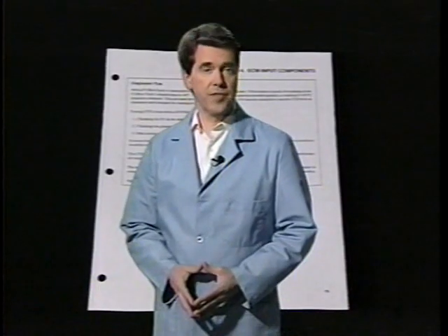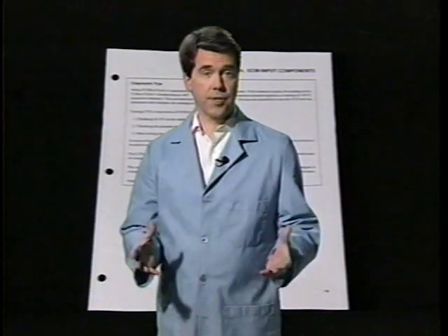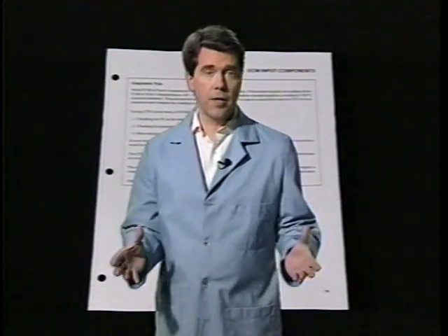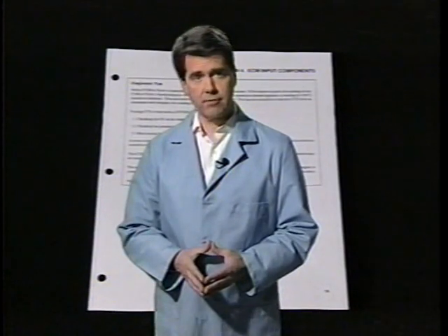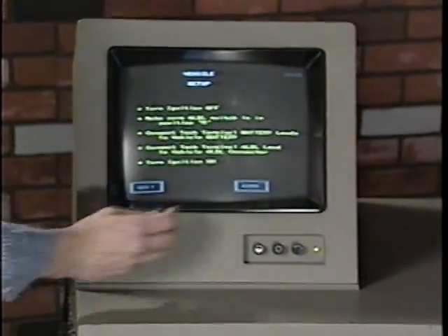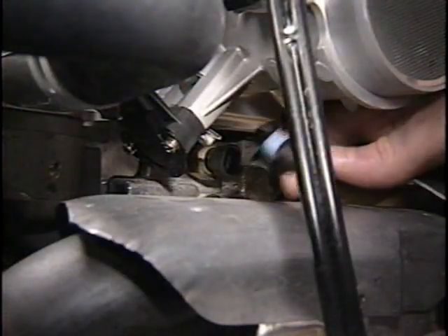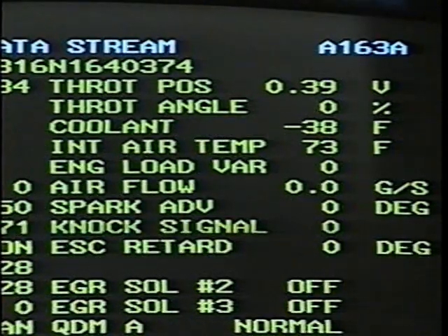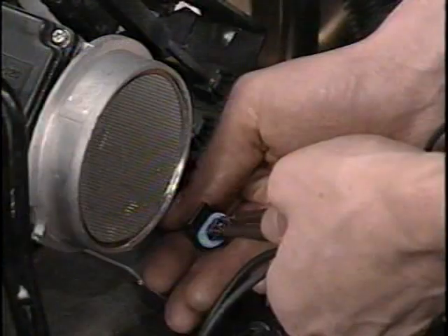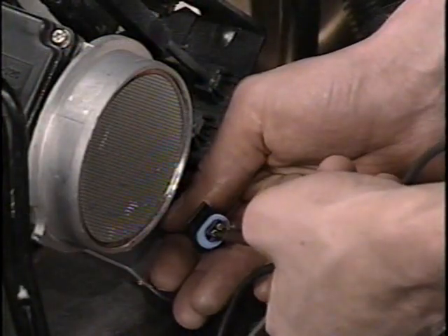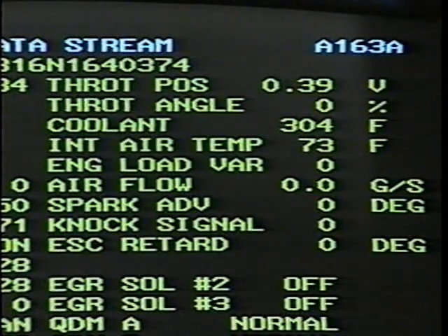The short sections of diagnostic tips for each sensor are not based on any one car, but are general enough to apply to all Buick fuel-injected engines. For example, if you connect the T100 to the vehicle and unplug the coolant temperature sensor, you should see a reading of -22 degrees Fahrenheit or lower if the ECM-PCM and related wiring are good. Likewise, jumpering the two terminals together should produce a reading of 266 degrees Fahrenheit or more.